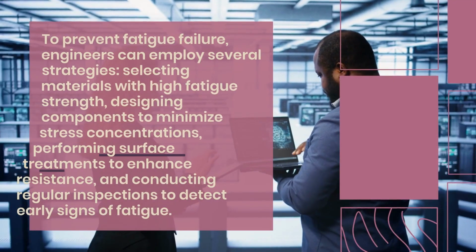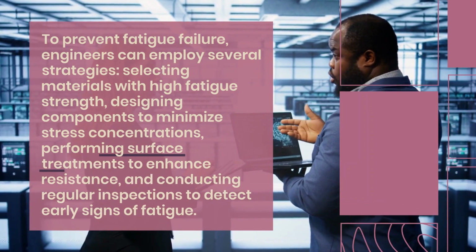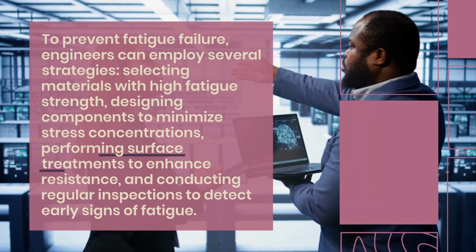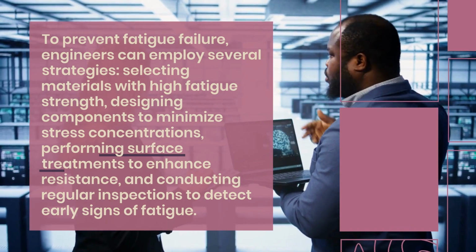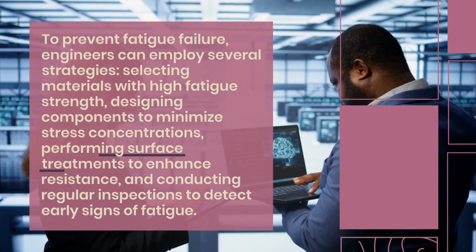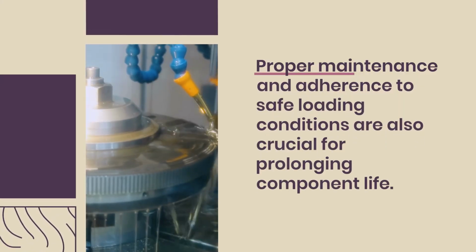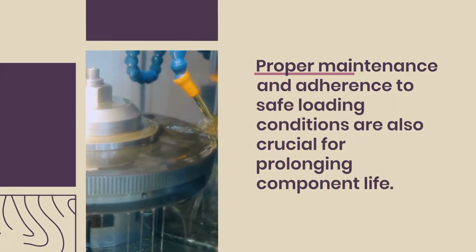To prevent fatigue failure, engineers can employ several strategies: selecting materials with high fatigue strength, designing components to minimize stress concentrations, performing surface treatments to enhance resistance, and conducting regular inspections to detect early signs of fatigue. Proper maintenance and adherence to safe loading conditions are also crucial for prolonging component life.